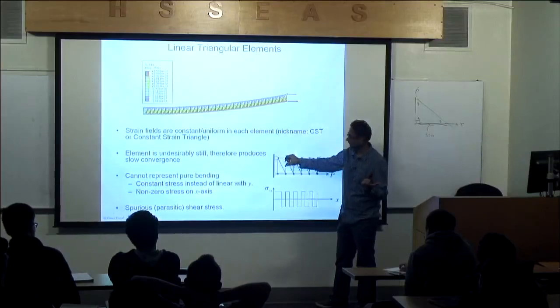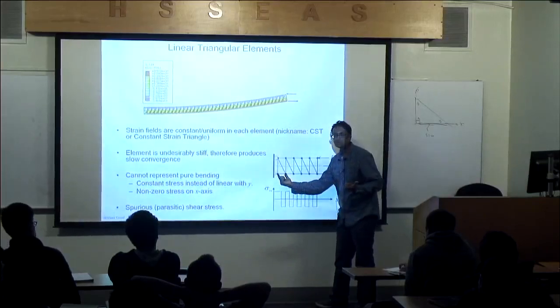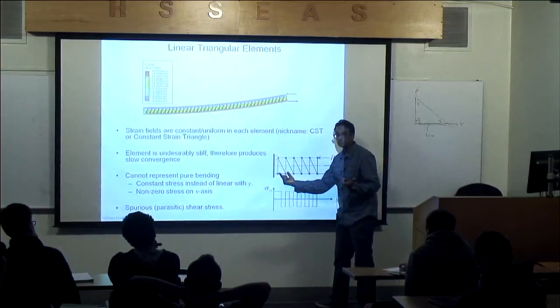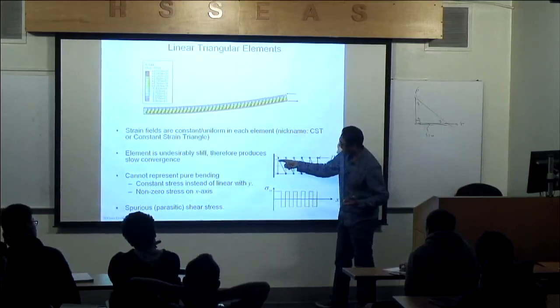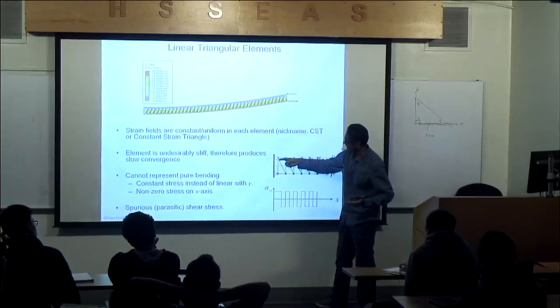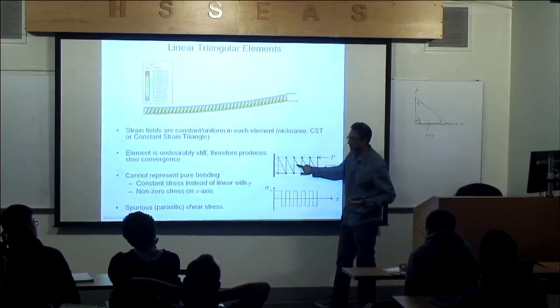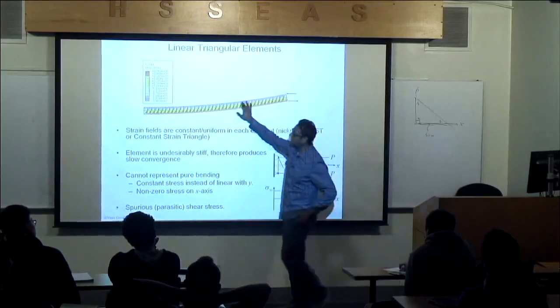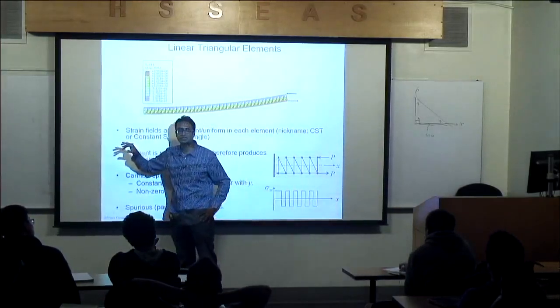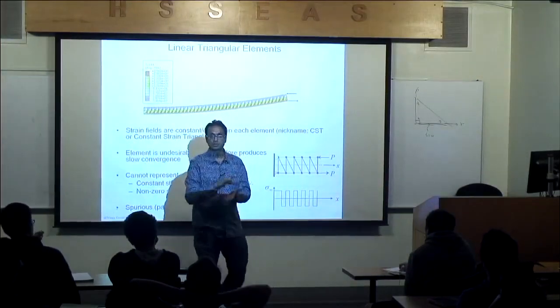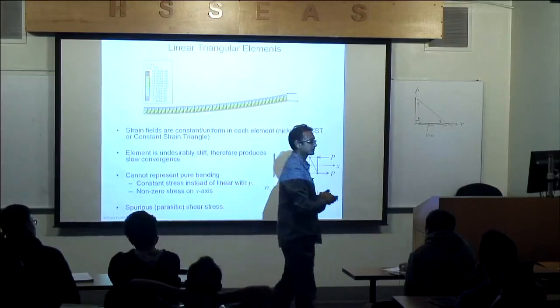The bottom edge is going to sense that it's in tension. So now this whole element will be positive tension, and this whole element will be compression. You go positive, negative, which is what you're seeing here, but to a lesser extent, because we're using more elements through the thickness. Does that make sense?